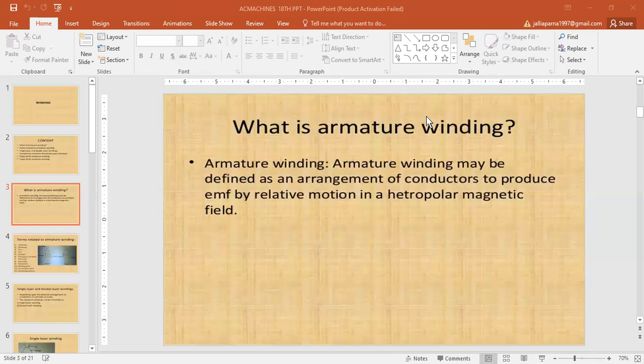As a matter of precaution, it should be kept in mind that all these pitches, though normally stated in terms of armature conductors, are also sometimes given in terms of armature slots or commutator bars, because the commutator is after all an image of the winding. The commutator pitch is denoted by YC.